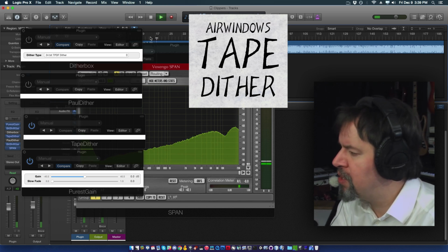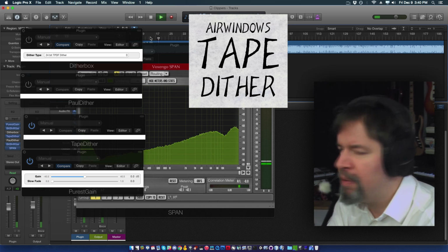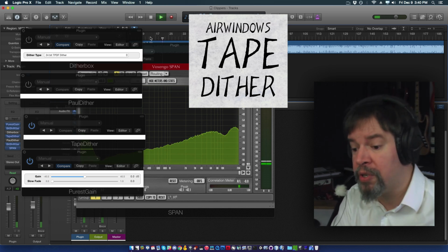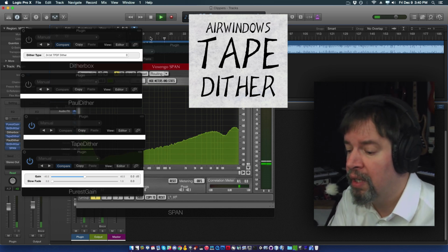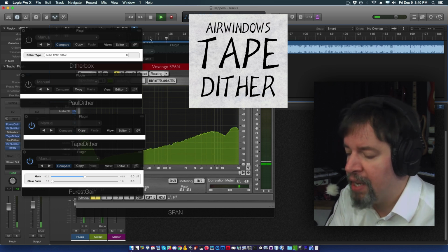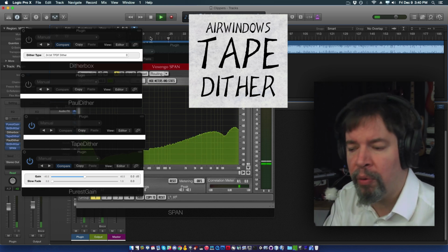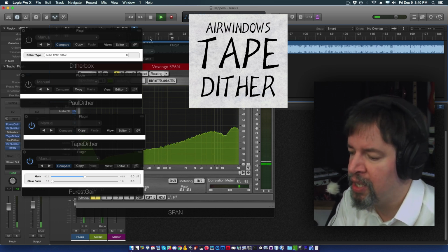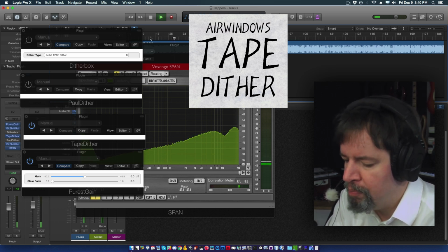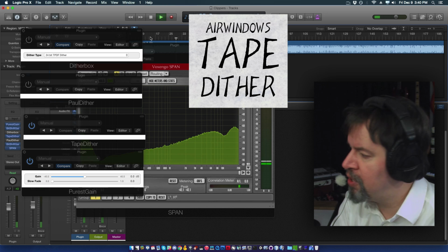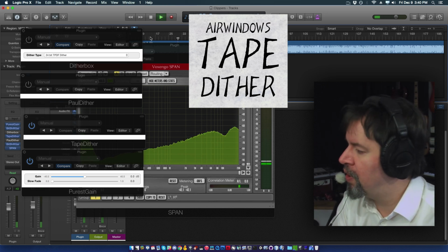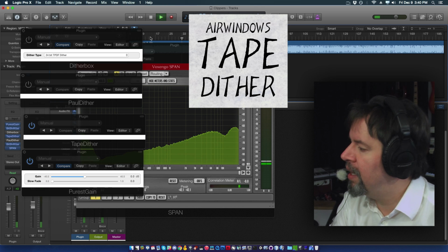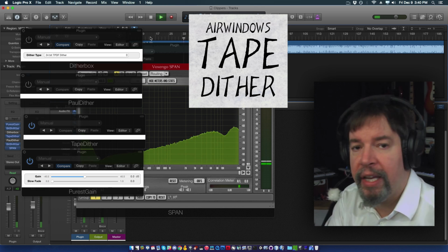You can plainly see how there is this dip right around 10K. And that's not so unusual because I was researching how tape machines do their biasing and the tape noise, the pre-equalization, the post-equalization. There's a lot of different ways that tape machines minimize noise, but this is pretty fundamental to them, that there is a pre-emphasis and then there's a roll-off, and it'll often kick in around here.